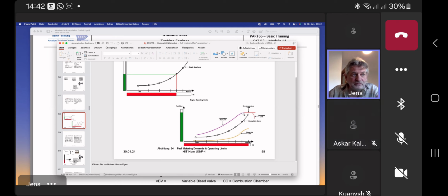If the engine would enhance the fuel flow too fast, there will be a lack of cooling air. Therefore, we are at risk of over temperature. Or otherwise, we go to overspeed. At these RPMs, especially for the N1, the fan blades also carry weight, and the turbines have more material, so more centrifugal forces. We cannot take the risk that we go into overspeed. Otherwise, we would maybe have a blade separation. So in this case, we talk about fuel enhancement.